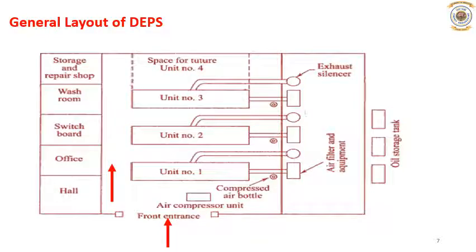The repair and usual maintenance works connected to such engines require sufficient space around the units, and consideration should be given to the need for dismantling and removal of large components of the engine and generator set.